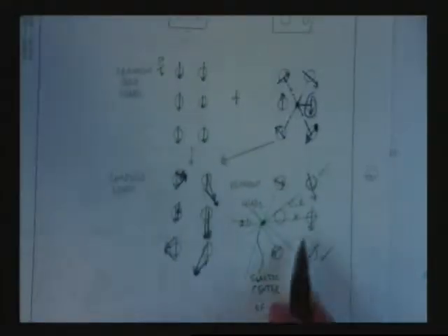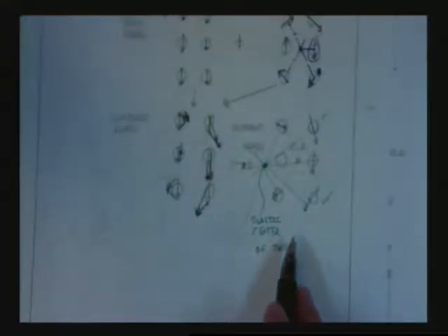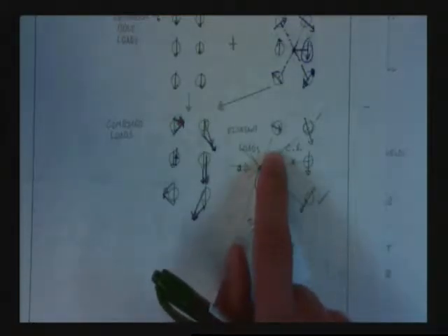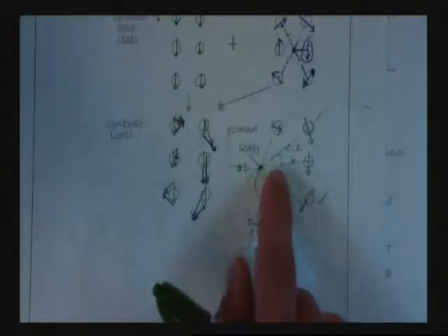What are we talking about? Well, those pictures I drew. If we come up with this idea and concept that when we drew this, if this is the limit state, if this is it, there is no more. We have this bolt that we're not even really loading. Then why is it there? Let's just take it out, right? Well, one actually could, if you're using this elastic analysis, and you'd get no difference in calculated capacity. But that doesn't make sense. How can you take a bolt out and have it not add to capacity? That doesn't make any sense at all.